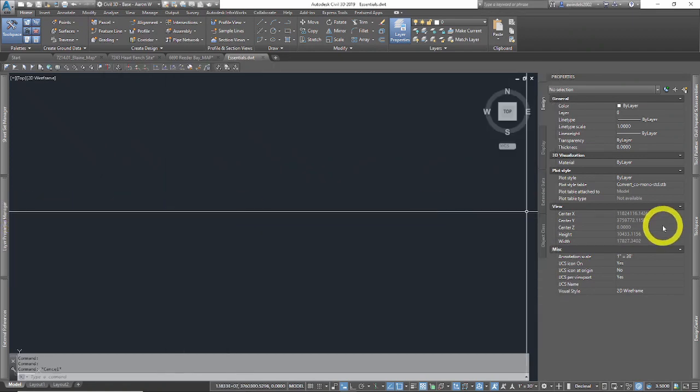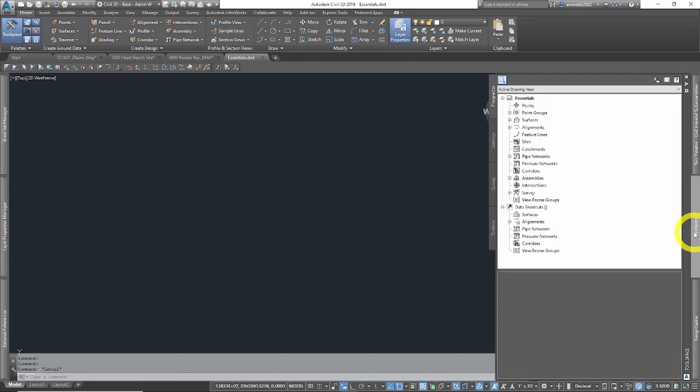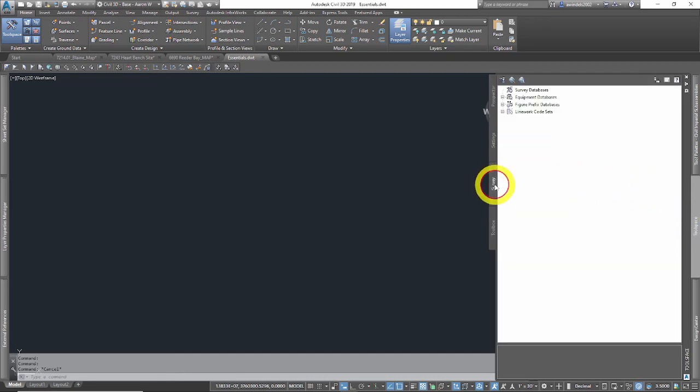We're going to start by going to the Survey tab in Toolspace. Toolspace is our home base for most things Civil 3D we've been learning. We're going to go to the Survey tab, and we're going to start by making our working folder known. You have to change this between jobs. When you switch jobs to different areas in your file structure, you need to change this, much like data shortcuts when you go from project to project needs to be changed too.